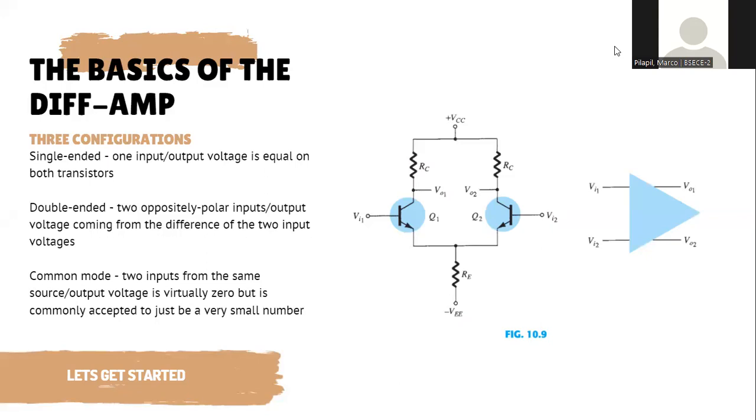The reason for this is because there's only one emitter current that runs through the entire circuit, and it is divided into two collector currents that go across the left and right side of the circuit. So basically IC1 and IC2. And since IC1 and IC2 are exactly equal, since they are the equal halves of the emitter current, they run through the same value of RC.